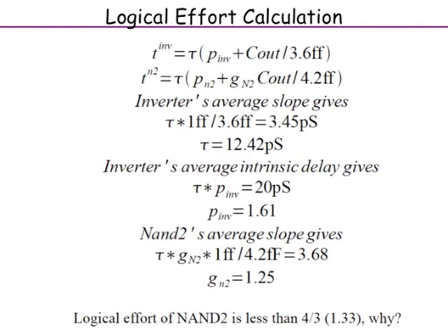Now one thing you notice here is that in the hand calculations in the previous lecture, where we had sized the NAND 2, we said for the pull down stack, if you want to have the same drive strength, we'll make the NMOS 2 and 2 because there is a series of 2. Each one has R by 2, so the whole thing has R, same as that of an inverter of size 1.